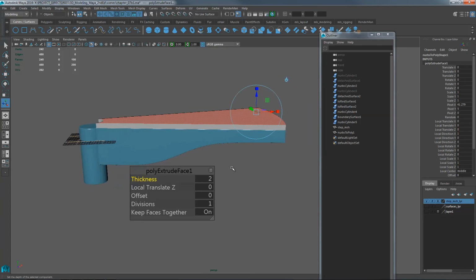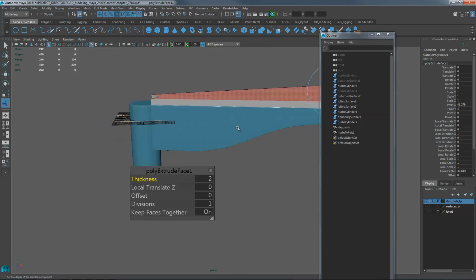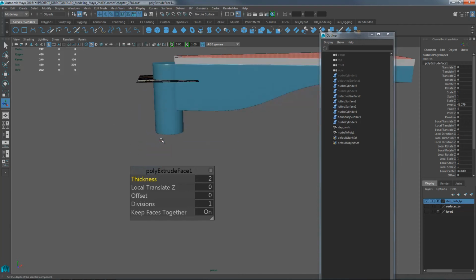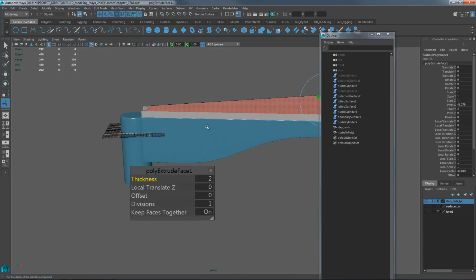Proportions. Good proportions. That will change our riser to be 21 centimeters because this is 2 centimeters thick, clipping off 2 centimeters on our total cylinder height. So our riser is going to be an actual 21. That's fine, according to the documents that we saw earlier.